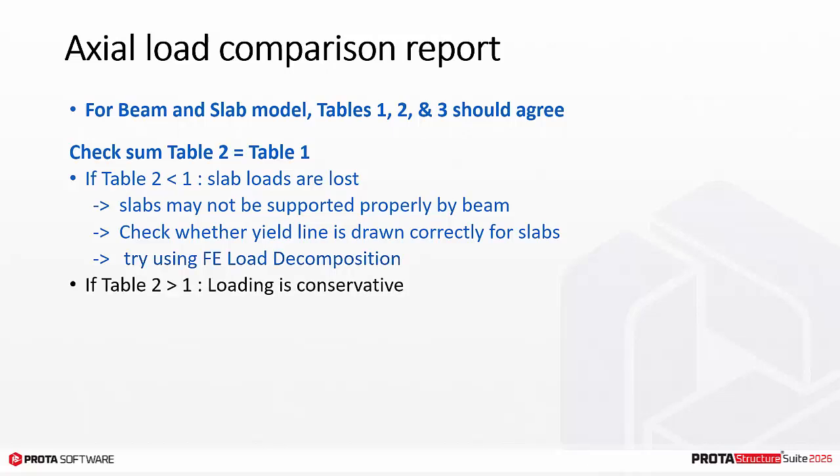If table 2 is more than table 1, slab load calculation is more than expected, hence conservative. However, if the difference is significant, then you should also go back to your model to investigate.